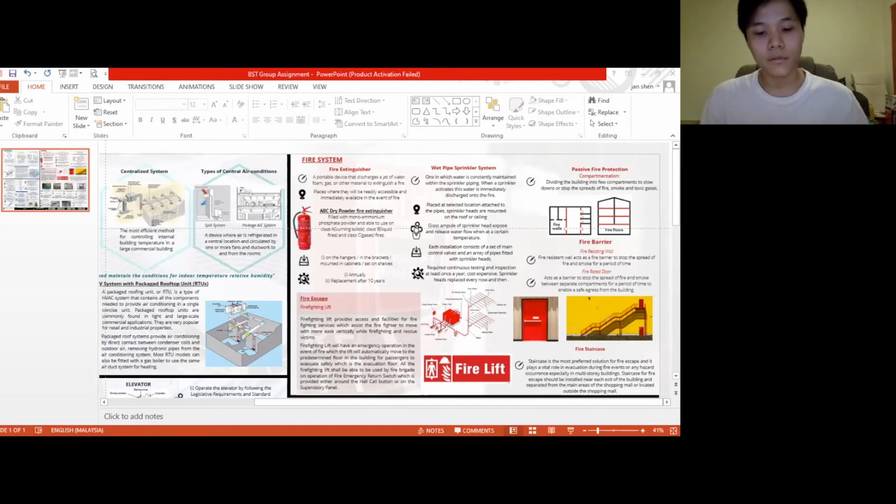There are two types of fire resisting wall: the wall giving support to the structure, and the wall that doesn't give support to the structure, which is the partition wall. These all use different materials. The wall giving support to the structure is constructed of concrete, and the partition wall is usually made up of several successive layers of non-combustible board, which must be properly installed to be effective.